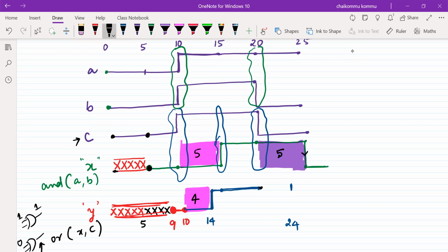You can find changes here up to this point. And here, what is happening? Again, it has to assign the value after another 4 timing units, but there is no change here again. Of course, up to this point it will be there. At 24 there is no change, so again it will be continuous. Now at 25, you can find a change here. That means another 4 nanoseconds it will take, that means 29. At 29, it will be 0.